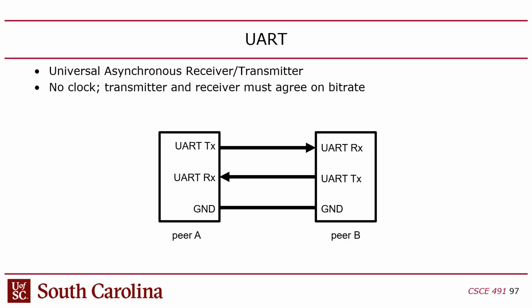You don't do that with UART, because with UART, you have to connect the transmit on one side to the receive on the other. So the pin name on here is not the same as the pin name here, unlike in SPI where the pin names match, right? So this is sometimes called a crossover or a null modem connection, I think, typically. If you get that wrong when you're wiring up your breadboard or making your circuit board, that's a pretty serious problem.